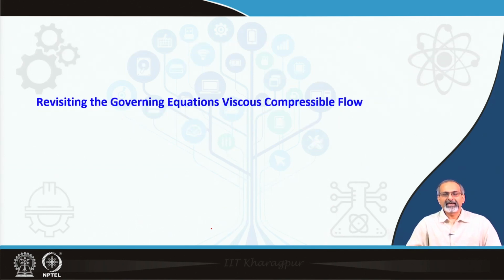With this, we move towards the end of this lecture by saying that we would like to now start revisiting the governing equations of viscous compressible flow, since we were talking about either boundary layer kind of solutions, which are applicable where we actually have a very thin layer of viscous flow developing on a body, or engineering correlations like the reference temperature method, which talks about extending incompressible flow results with compressibility corrections and trying to predict skin friction and heat transfer coefficients both in the laminar and turbulent regimes.